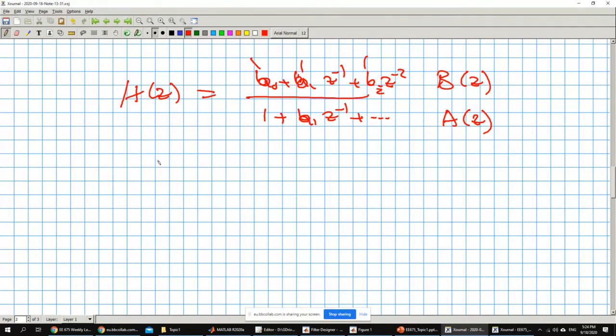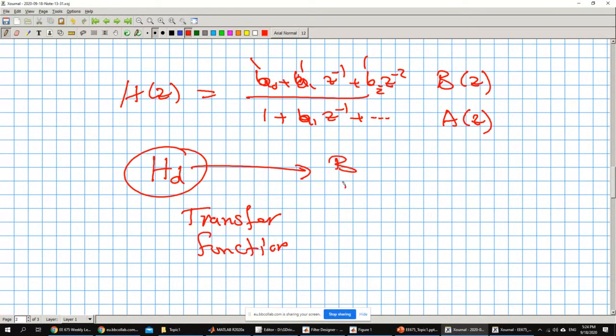So what we got from the filter design function was hd. It's in a special format for MATLAB. It doesn't really have b of z and a of z. There is a conversion function called transfer function that takes hd and gives you b and a. Okay, let's try that. I'm going to go back to MATLAB and try that.